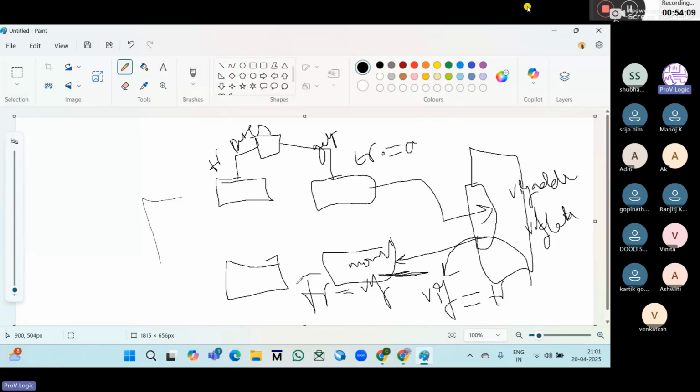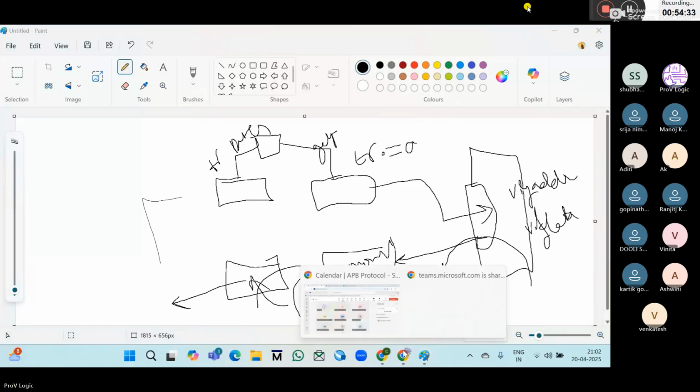Okay, so monitor will get all the data. Now this transaction data is sent to the scoreboard via mailbox. In the scoreboard, we write the output to print in the log file. We write the display statement, and also we do the comparison. Comparison logic you can also write, because in scoreboard mostly we write the checkers, right? Last time I showed you an example in the I2C protocol of how we write the checker. The same way we can write.